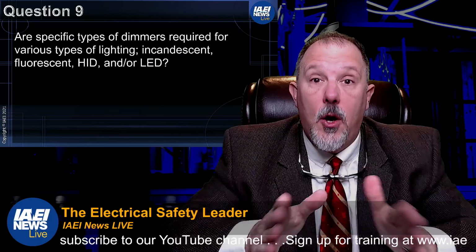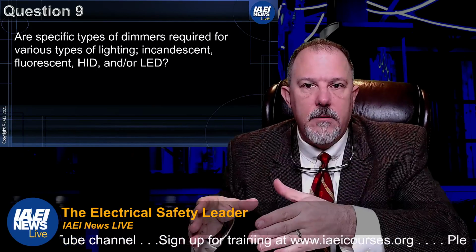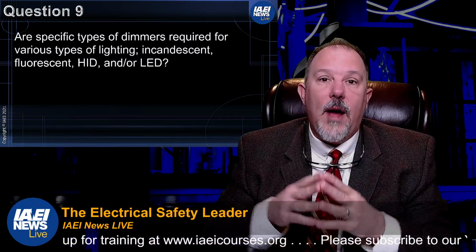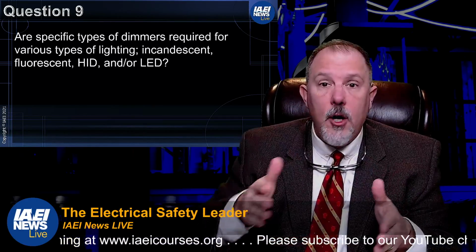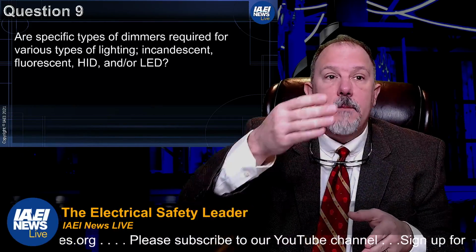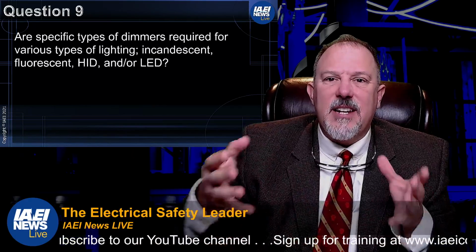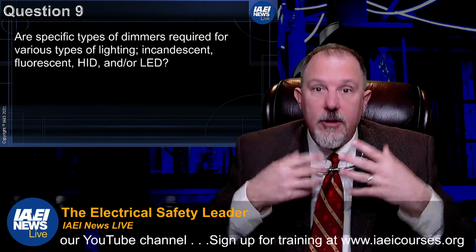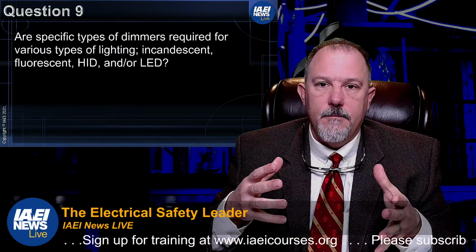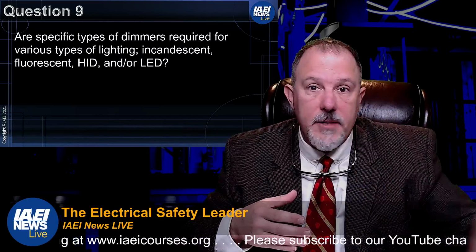Now, we already know that each type of lighting load will have characteristics. What have we talked about so far? We talked about HID, high intensity discharge lighting. It will have a current signature, a current draw, with a power factor that we need to consider when we select our overcurrent protective devices.